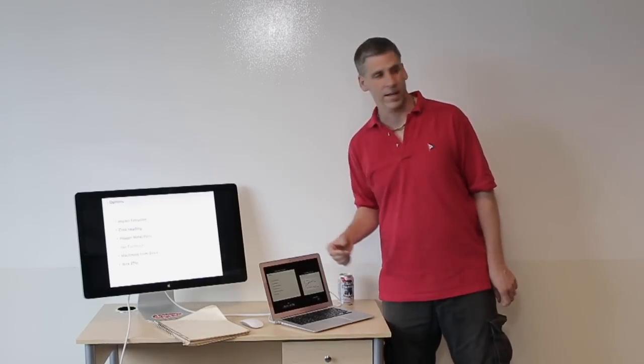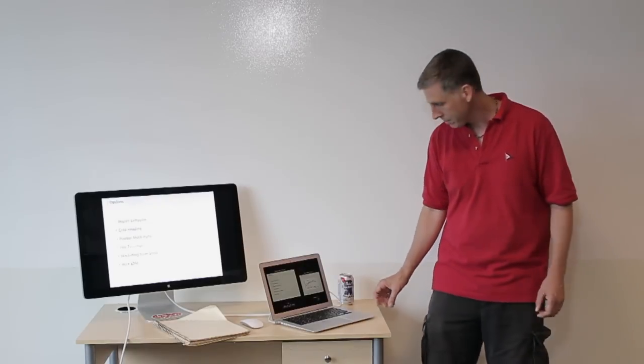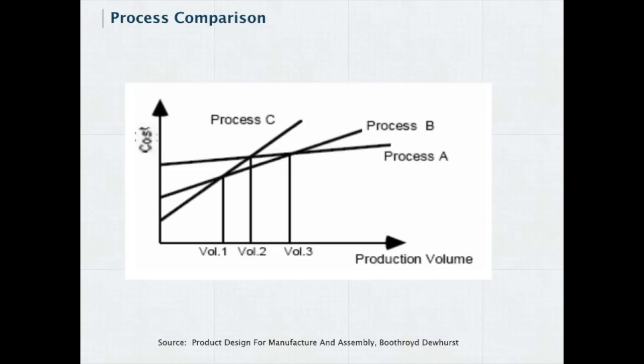And you may look at that and say, well, these are all options, but really for what I'm trying to do, extrusion makes the most sense when I look at it, assuming you wanted it to be metal. It's a classic extruded shape. Or wire EDM, depending on how thick it is.